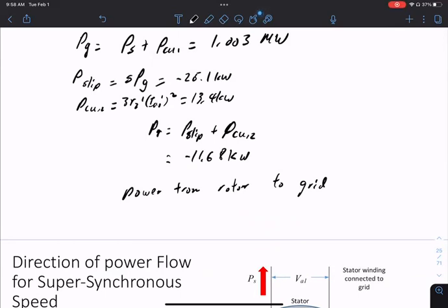Good. In this problem, the angle theta S, wouldn't you want theta S to be as small as possible, ideally? Yes, you want to minimize theta. Here theta is still quite big, so it's still quite a bit of reactive power. So here we did not regulate.